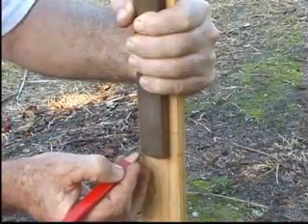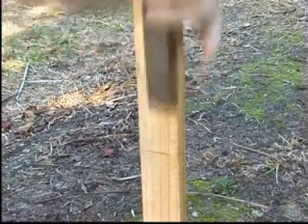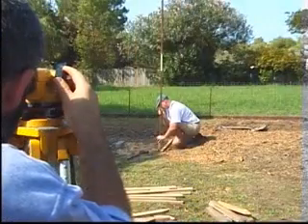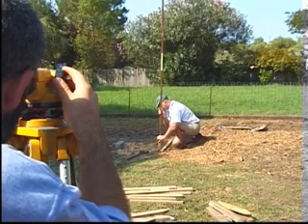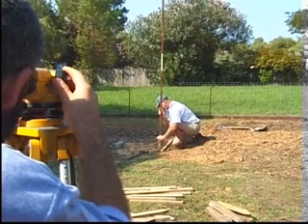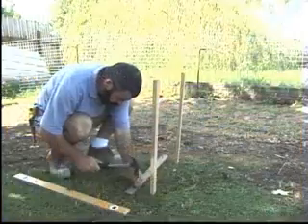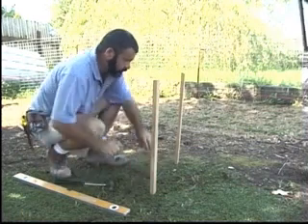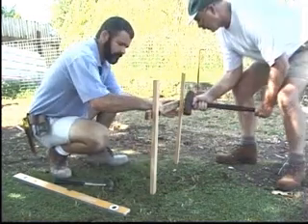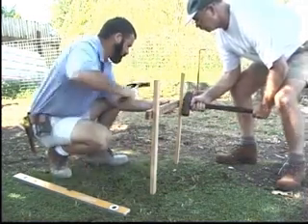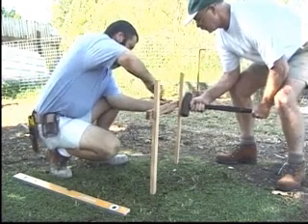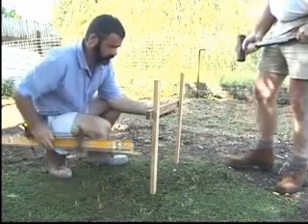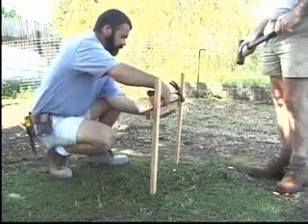This height is transferred to the legs of the profiles. Bring it up 20, up 10, too far, down 2, down 1, spot on. The tops of the ledges are fixed at these marks and levelled across the profiles.